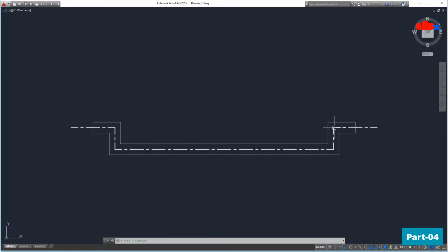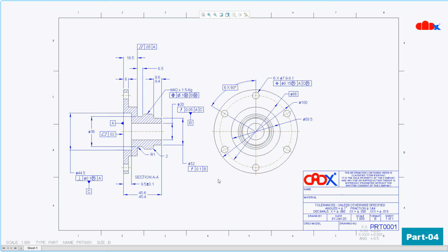Now you are telling that this axis should be concentric and straight within that range, within 0.05. So here you are telling that this axis can be actually out with reference of this axis within this range. So now one thing you will notice that everything is controlled by this datum A, this surface. If this surface tilt, this axis will deviate. If this axis deviate, this axis will also deviate.